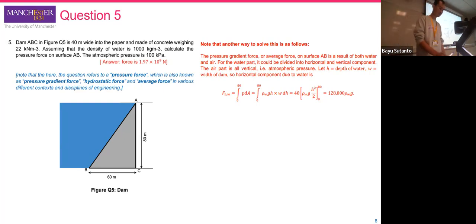So if we go back to the slide, for the horizontal force that is coming because of the hydrostatic pressure in the depth of the water, we can take the integral. This force is P multiplied by the projected area, where P is rho g h. Because we have information that the pressure is varying in its direction, but constant with y here.